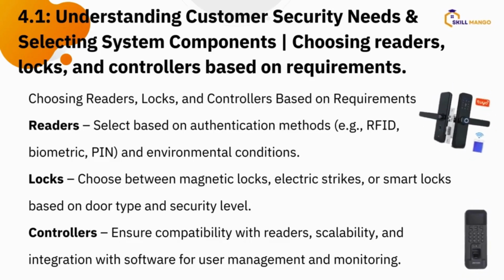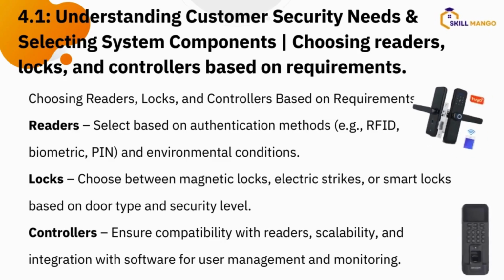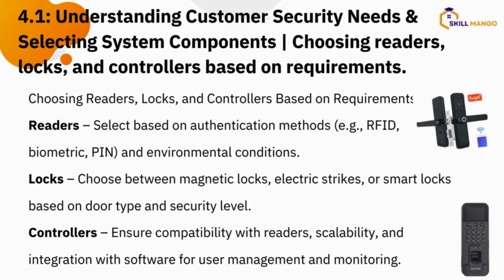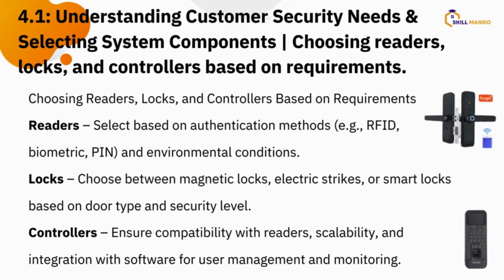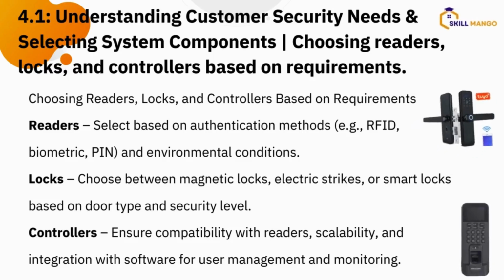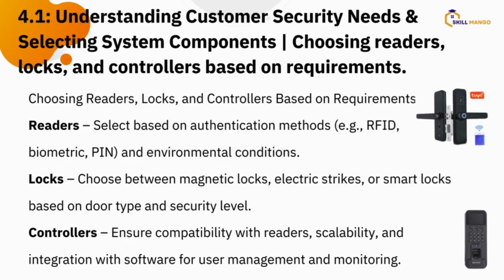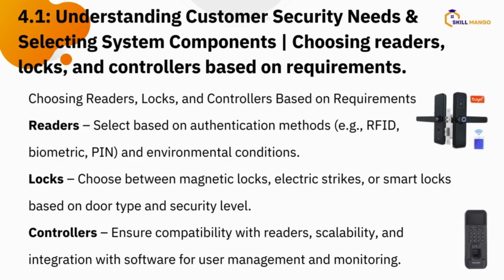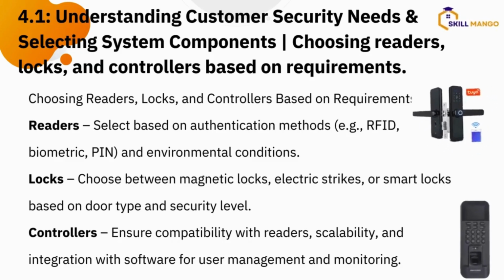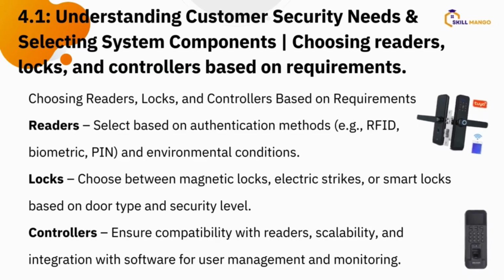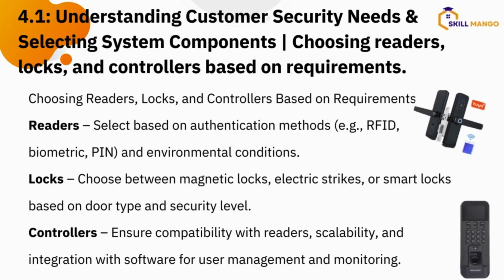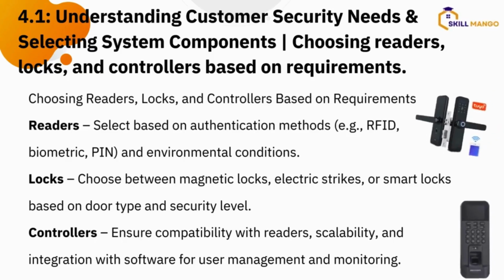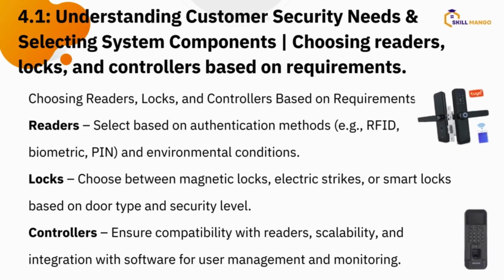All right. So you can use that to ensure that your door is well locked. And now it has advantage, it has disadvantage. This magnetic lock now, when there is power, is locked. When the power is out, let's say there's a power outage in the building, it is disengaged. You can now open the door and the door can be opened anyhow. When the power comes back, it sees power again, it contracts and nobody can open it again until you use the reader to open it. All right, that is a magnetic lock.